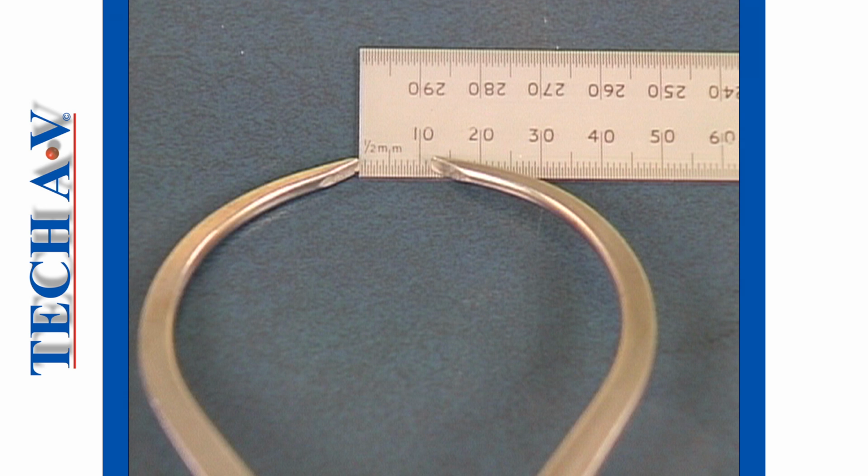One caliper tip is now placed against the flat end of the rule. Then, laying the caliper as flat as possible, line up the other tip to your 0.5 millimeter rule scale and read the rule at the point where one of the rule scale lines is in line with the caliper tip.